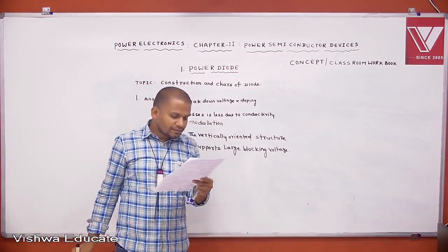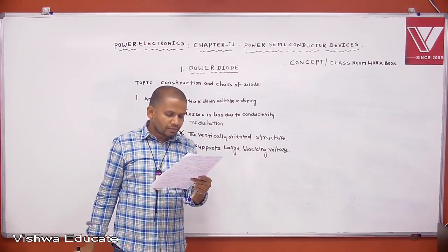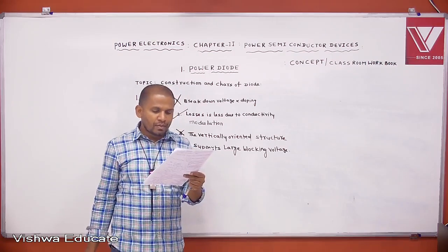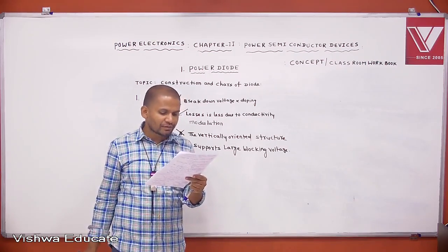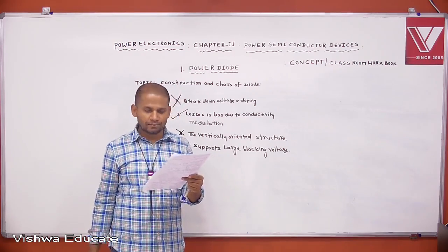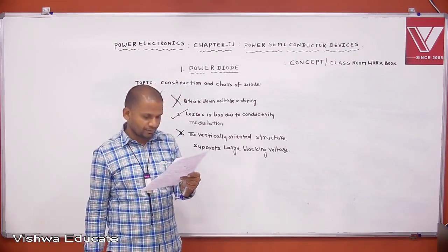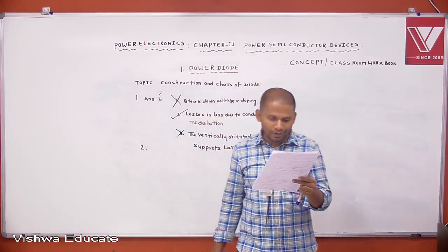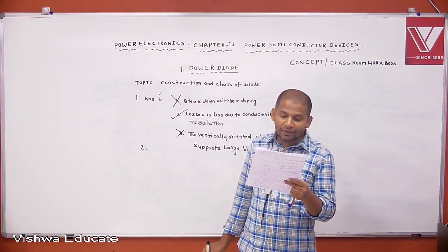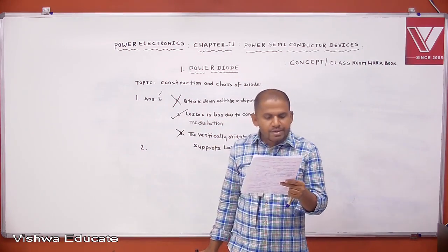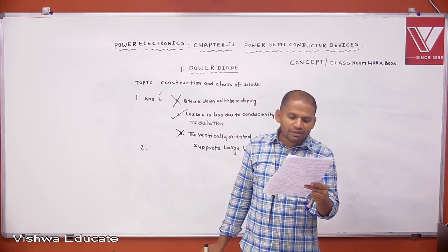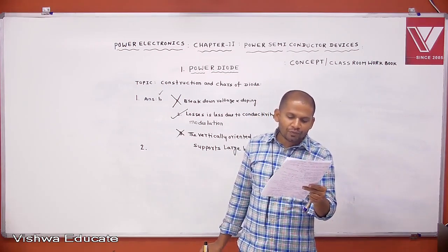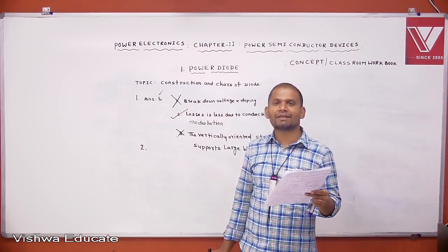A structure obtained by a lightly doped N-drift region between the layers of a PN junction, a PIN diode is obtained. The structure is effective in making the diode support large reverse blocking voltages, making the reverse recovery process slow, making the diode have high on-state voltage drop, reducing the voltage spikes during turn-off due to stray inductance.